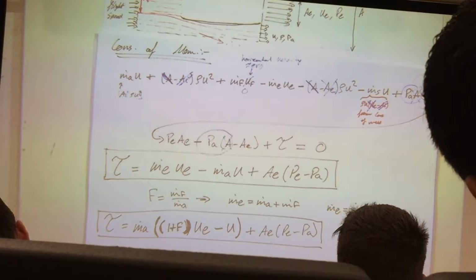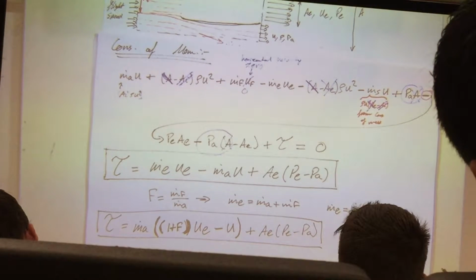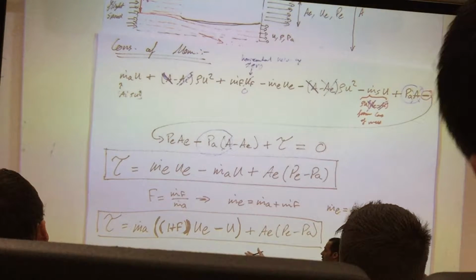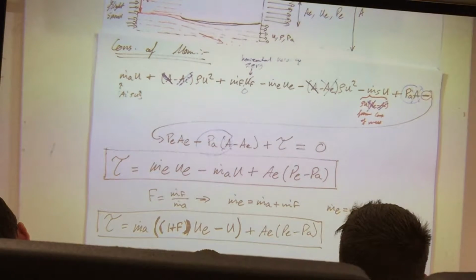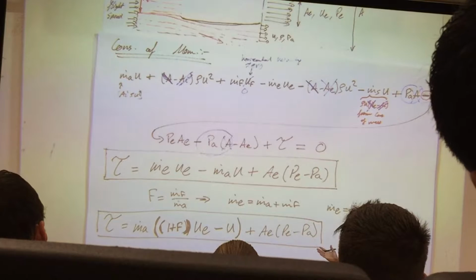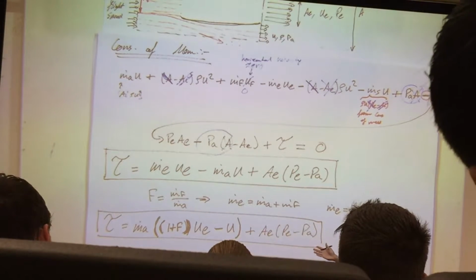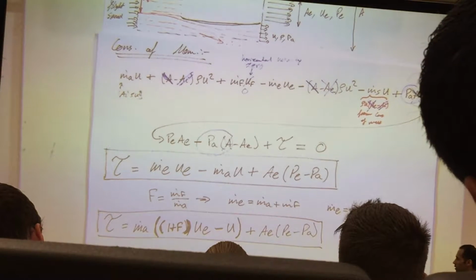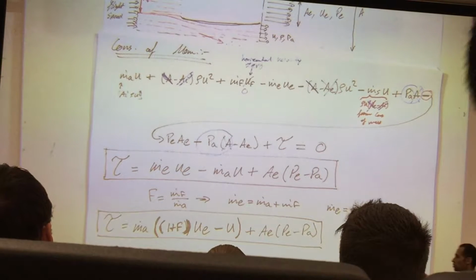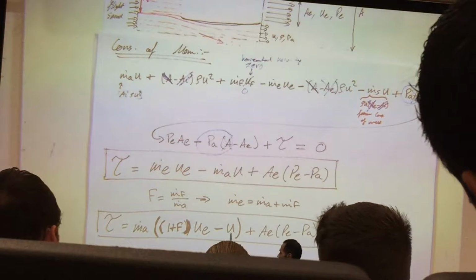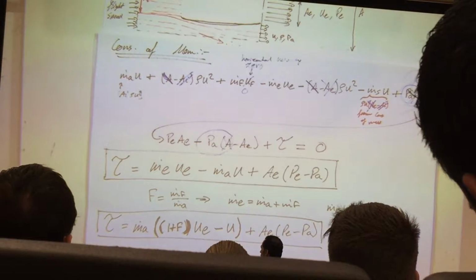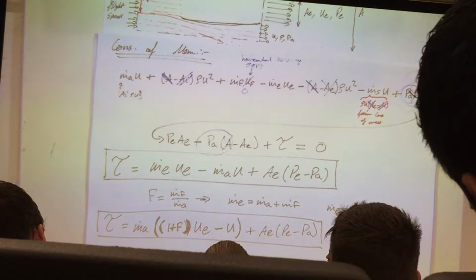So if I know, for an air-breathing engine, my mass flow rate going through the engine, which is a very critical parameter that you need to know, and you know your fuel-air ratio that you're putting in, then based on that, you get the exit velocity. You know your free stream. This is known because this is your aircraft velocity that you're flying at. This you're computing based on the condition that you're doing through a reaction.